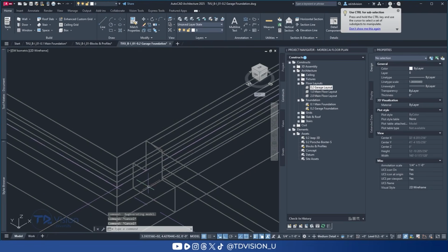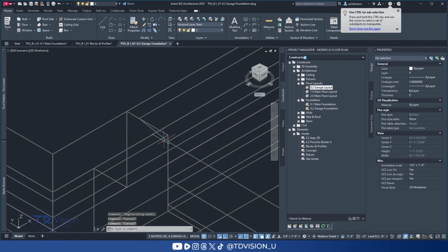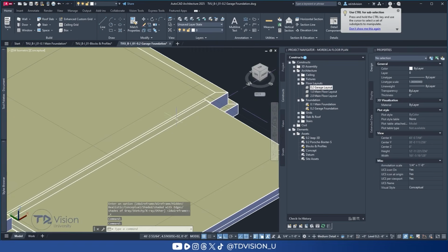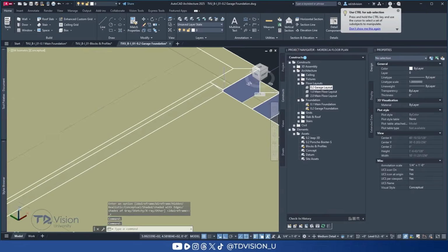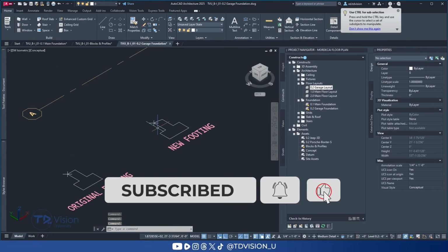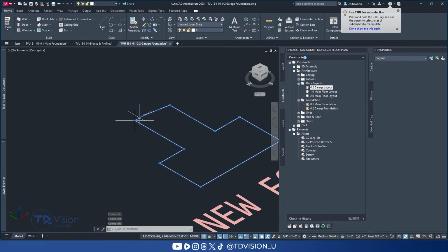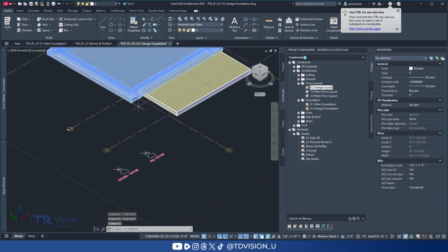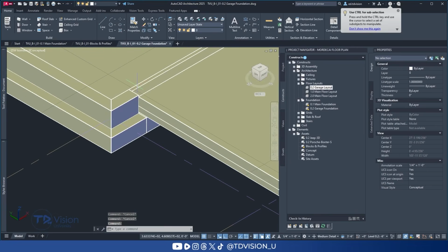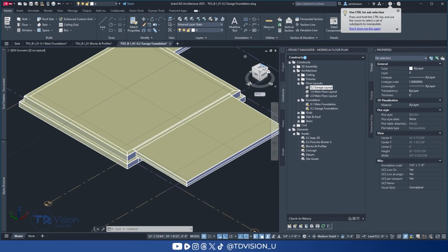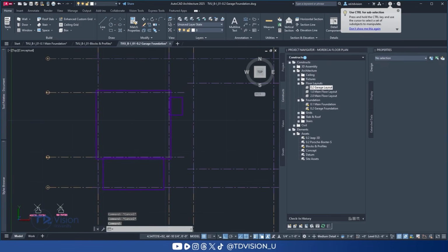If you go and look, you can now see that it converted into a slope, which is actually not bad at all either. So once you replace your profile, and that's a neat little technique as well. Once you replace that profile with whatever shape you decide, it will push itself through to all the objects that were using that particular profile. So just an extra little bit of technique there that you guys can run with.